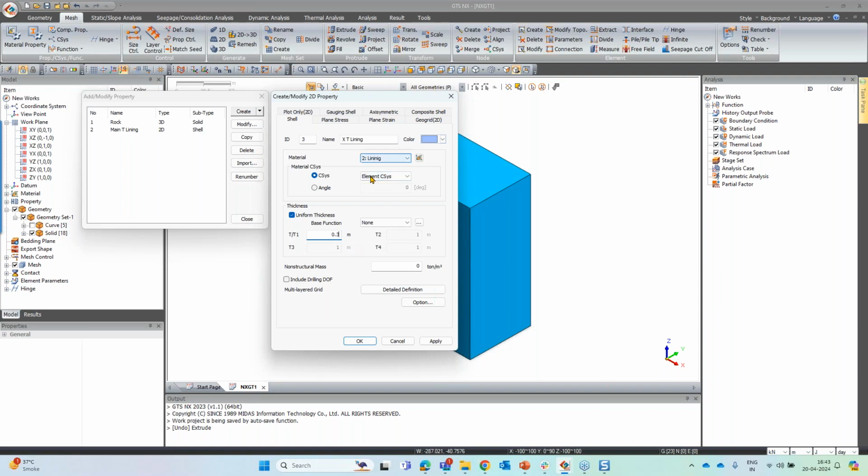So if you remember, I said we are going to relax the cross passage by 80%. So since we are reducing or relaxing the rock, we are letting the volume loss to happen. Hence, the stresses will be lower, hence the lower thickness. So the relaxation coefficients and the related study has to be done prior to this analysis, once the GRC curve, the LDP profile and the support capacity plots are drawn, which you already have gone through in the NATM session in this tunnel webinar series.